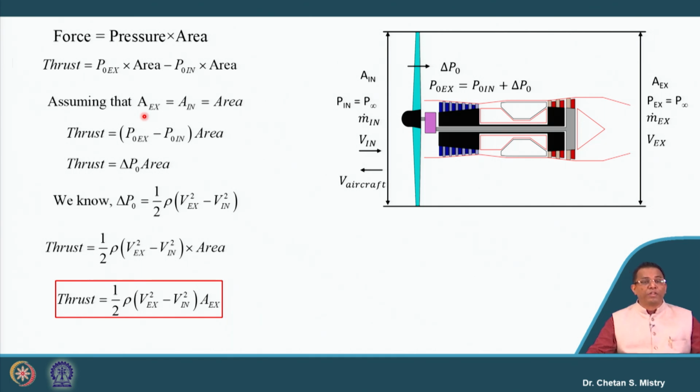So for a rough estimation of the thrust generation by the propeller, people most of the time use this formulation. They calculate based on this equation. Now these are the fundamental equations, the fundamental explanation that is available for the propeller. So when we are designing this engine or doing cycle analysis, most of the time people initially consider the propeller characteristics. And from there we can move forward to calculate the thrust generated by the propeller and the amount of power required to rotate that propeller.